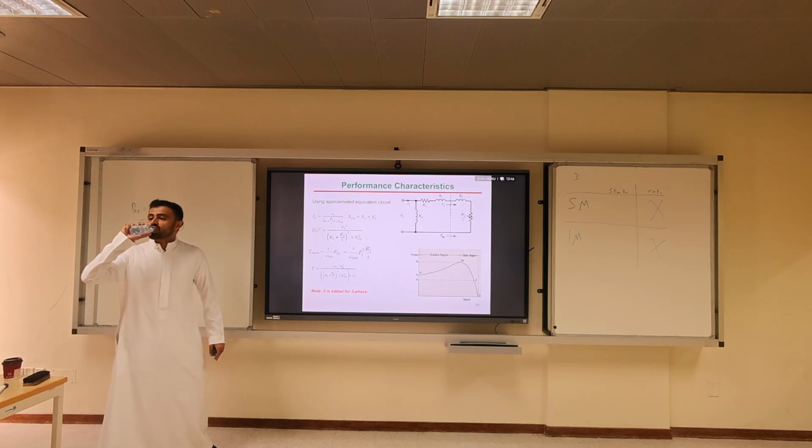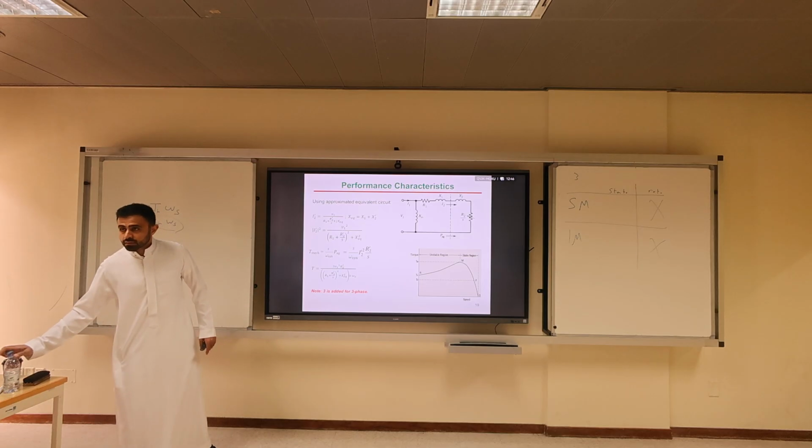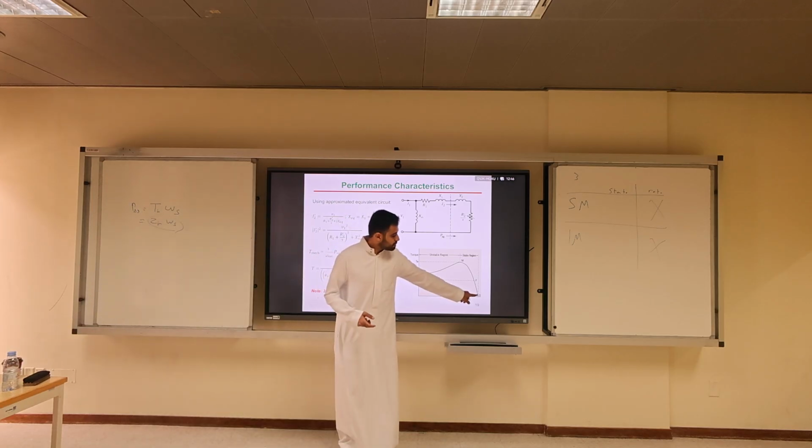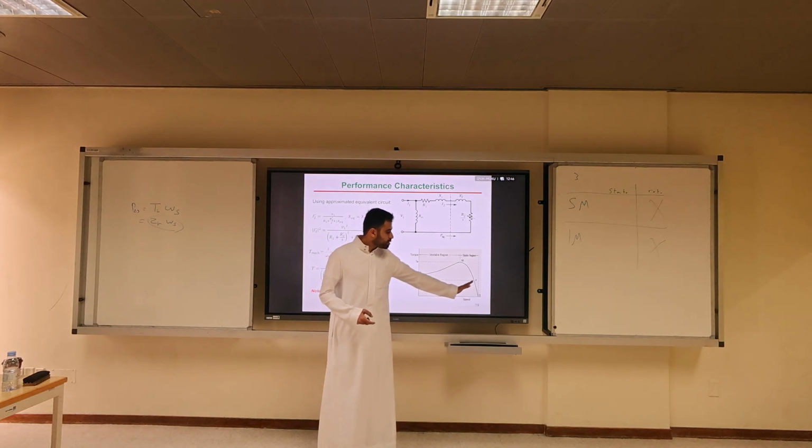No, you operate close to synchronous speed, depending on the torque that you need. If you need high torque, reduce the speed a little bit.